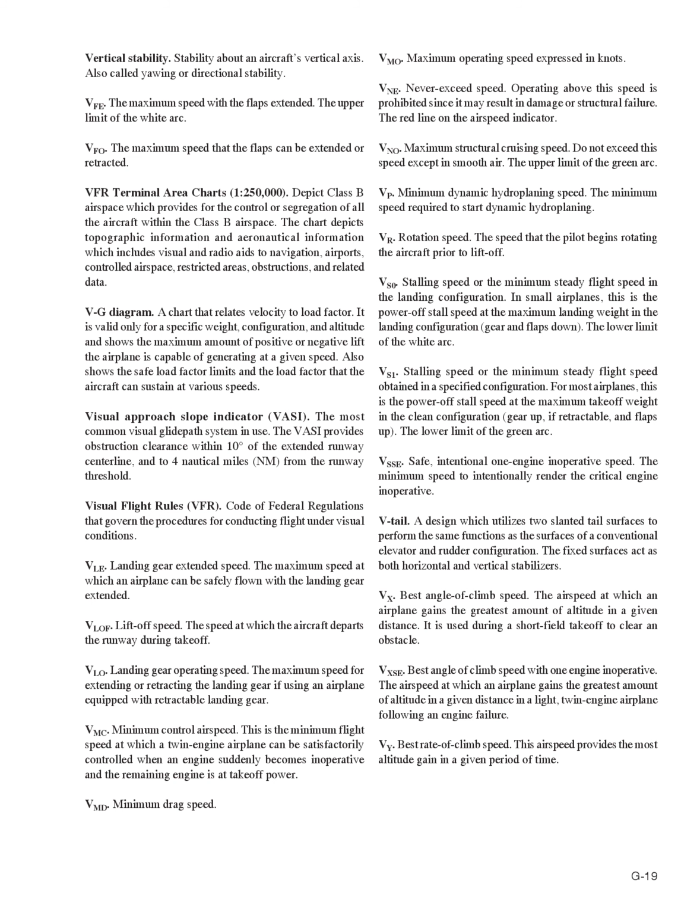VS1. Stalling speed or the minimum steady flight speed obtained in a specified configuration. For most airplanes, this is the power-off stall speed at the maximum takeoff weight in the clean configuration, gear up, if retractable, and flaps up.